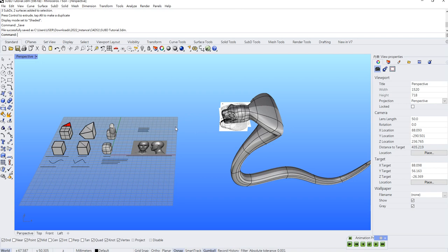If you want to make some organic model like human character, animal, or probably some fluent free forms, the best solution you can do is using subdivision modeling. But unfortunately, subdivision modeling is not a very precise and accurate way to do the model. So usually, industrial designers or architecture designers don't use this one that often.